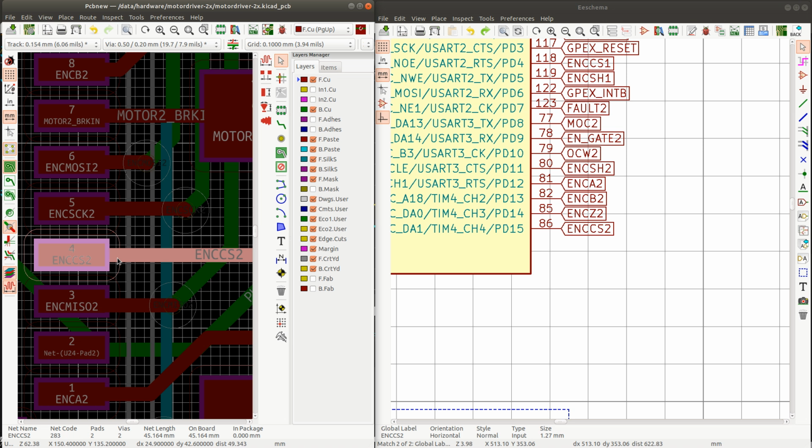So I'm gonna check the clock now. I mean, it could be that it was another chip just responding, because even though there are resistors, it could actually still be some other chip that responds. But we do see the signal from the other chips, but it's kind of like it's not going all the way down to 0. So it's kind of hard to tell. The only way to tell would be to remove the resistor and check if it's actually this chip that's responding.